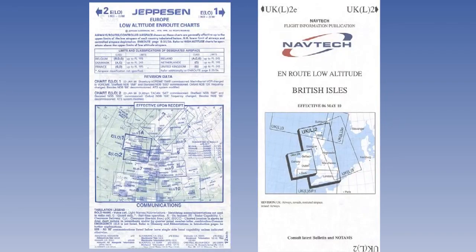For this sort of intermediate complexity aircraft, it becomes necessary to plot on a radio navigation chart, or a specialist plotting chart, usually a Mercator's chart or a Lambert's conical orthomorphic chart. The EASA ATPL requirement is for the use of the Lambert's conical orthomorphic, and occasionally the polar stereographic.